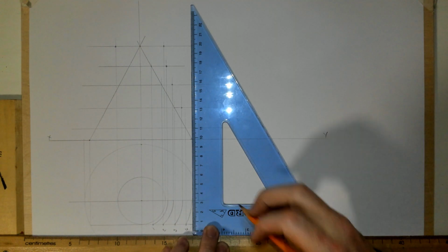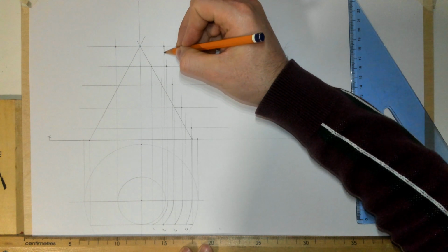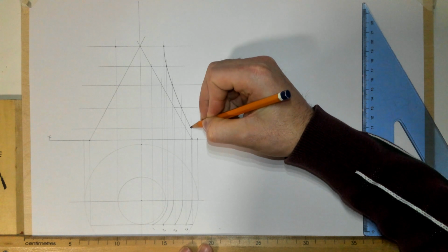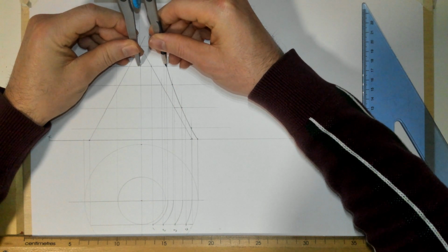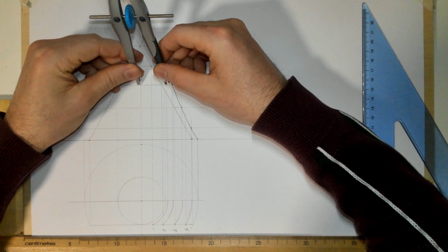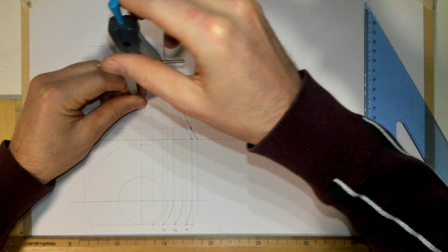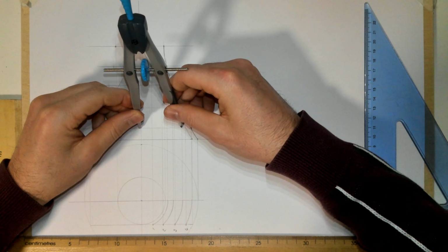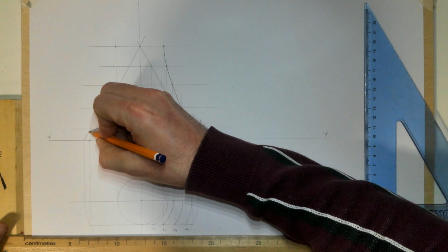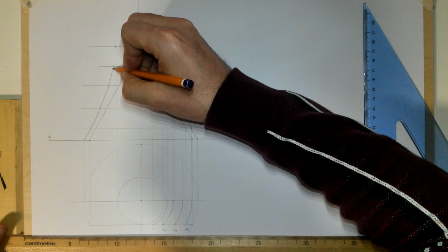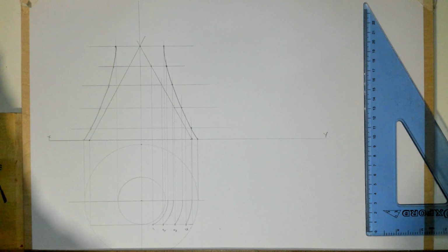That one was 3, and that one there was point number 4. And then it joins back to the very outer edge there at the bottom. So I can then draw in that curve just by joining the points. Left hand side then will just be a mirror image across, so I can mirror each one of the points over to the left. And same as the right, just join the points then. Okay, that's front elevation and plan view of the hyperboloid of revolution part drawn in.